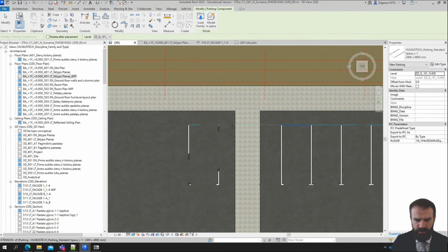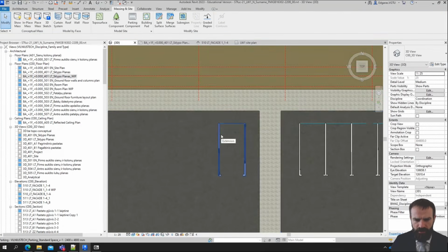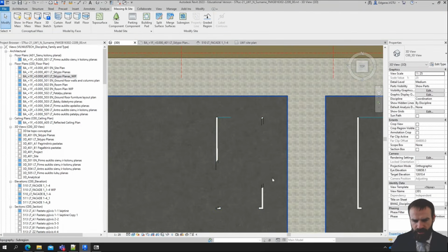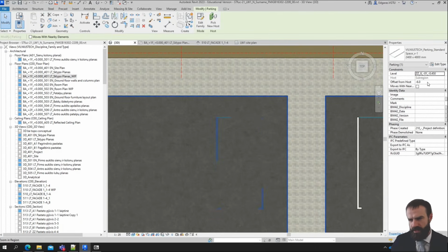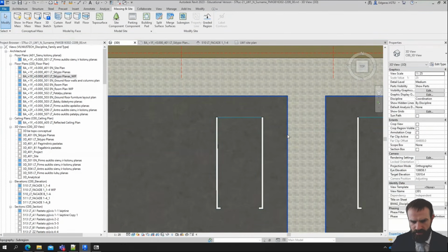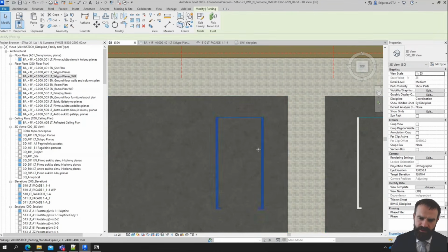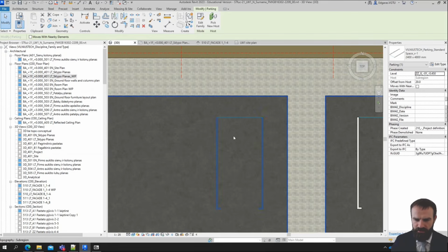So I put car parking here, and you can see the symbol is going inside my ground, so it means I need to lift the object a little bit up so all the elements are visible. Because the ground is deformed and the object is not deformed, if I put it on my ground, it will not adapt to the ground surface.